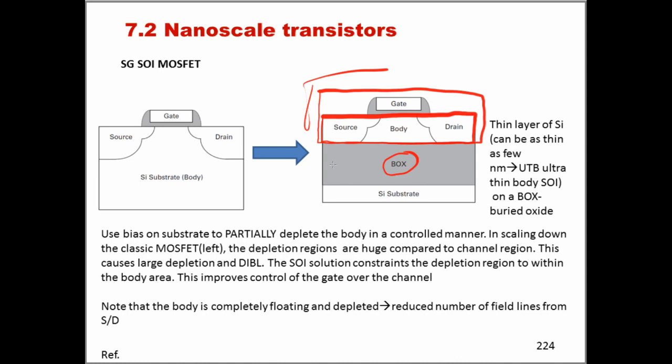Now this configuration achieves something extraordinary. The idea is obviously extremely simple, but is extraordinary in a way, because now the gate is in full control of the body, and there is no piece of this silicon material that is beyond the reach of the gate.